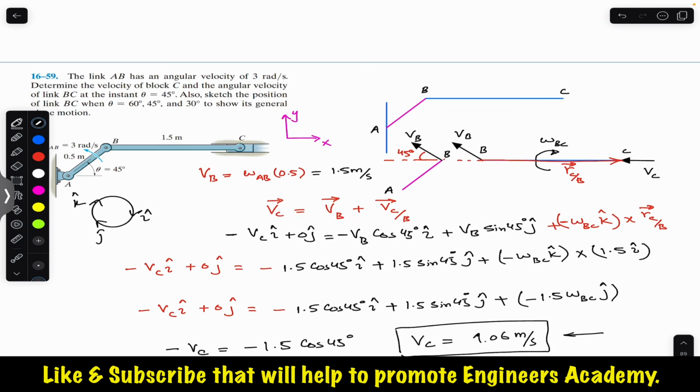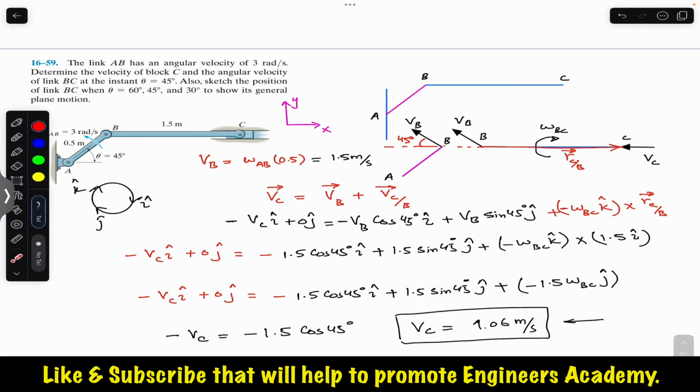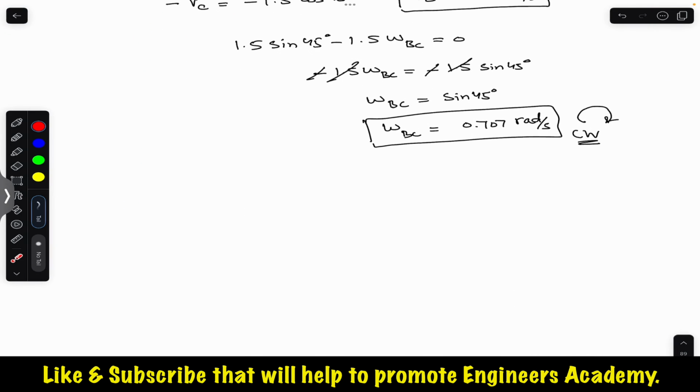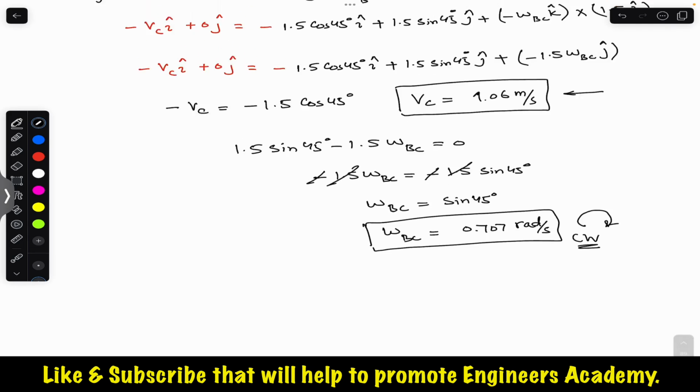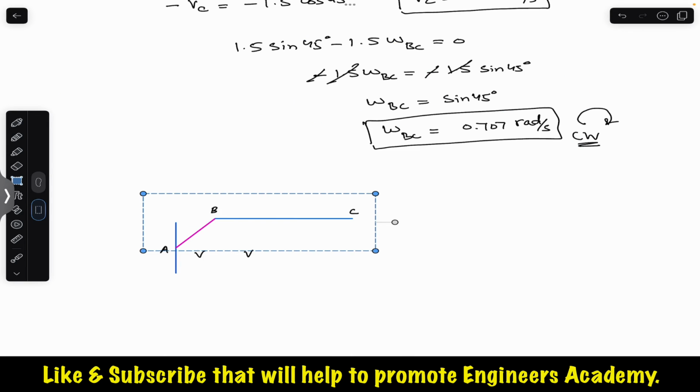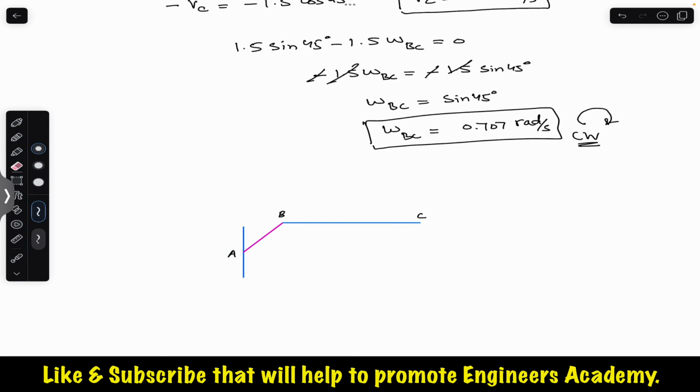Now in the problem statement, we are also asked to sketch the position of link BC when theta is 60, 45 and 30 degree. So let me draw the approximate diagram. First of all, let me copy this. This is the free body diagram. Initially this angle is 45.